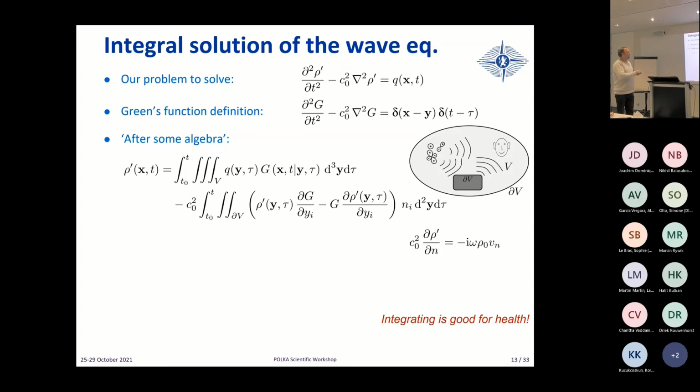So in other words, the sound field collected by your listener has this component here, which is the directly radiated sound field from the sources, and then another source term that corresponds to the sound that was going towards the solid body and reflected back to the listener. Now, I said that if the table is not vibrating, this one goes to zero. The problem that you have is this one. So how do you effectively treat this one? There's one way to solve the problem.